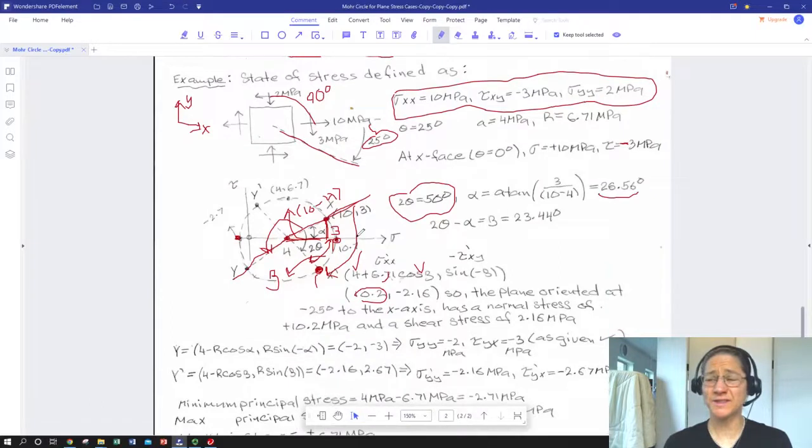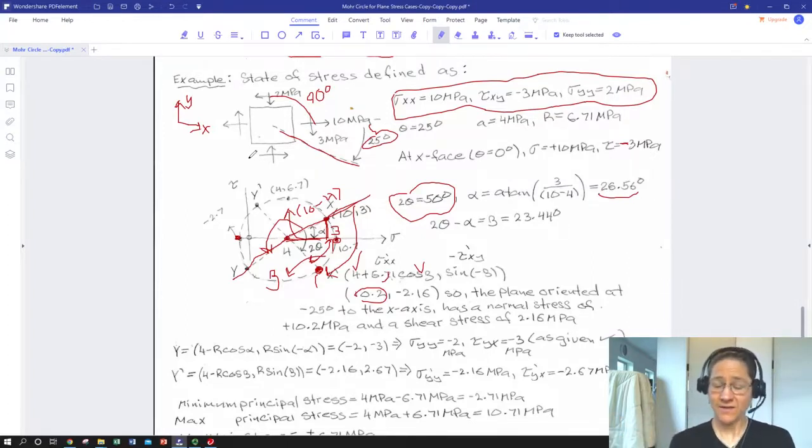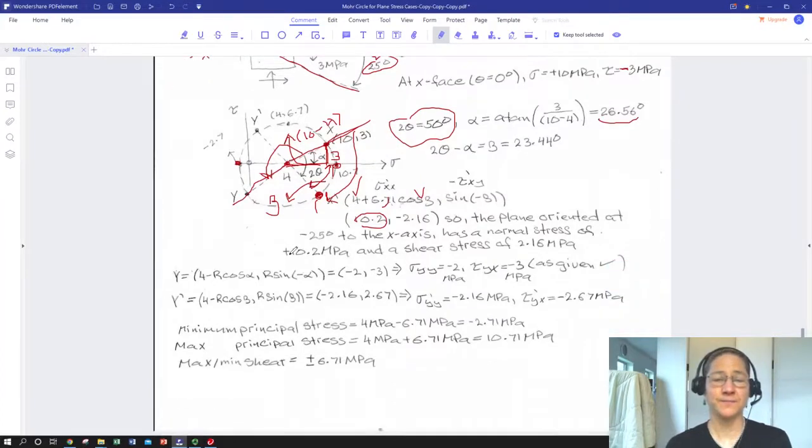So really there's almost a checklist of rules with Mohr circles that allow you to graphically use your stress transformations. Your center, your radius, the fact that angles in the body correspond to 2 theta on the Mohr circle, and just the simple graphical realization that if you're on the x-axis, you have no shear, and the radius of your circle is always going to correspond to your maximum shear at whatever angle that is.